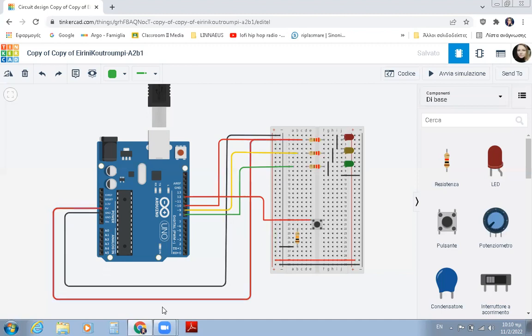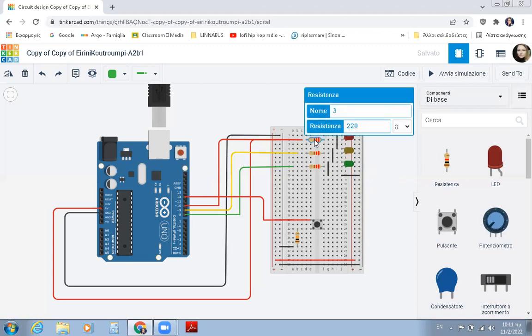Then we need to connect the two sides, as we said before. I choose 3 LEDs. I put them this way: cathode to the ground, anode to the power. And to make it work, we also need 3 resistors that protect the LEDs, 220 ohms. And we need some power. We connect the cables like these.